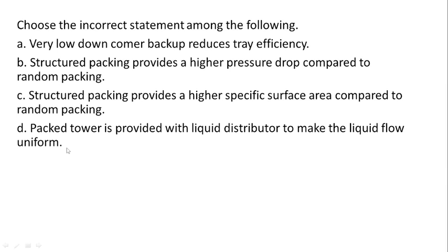Sir, because it is uniform, we know how much pressure drop will occur in structured packing. Okay. So the pressure drop will be lower in structured packing, and it will have high specific surface area. Here they have written the pressure drop is higher. So option B is incorrect.